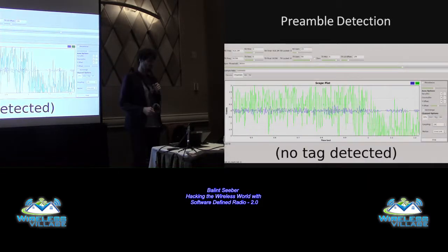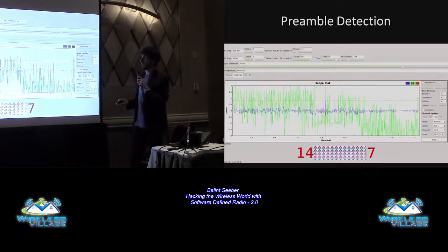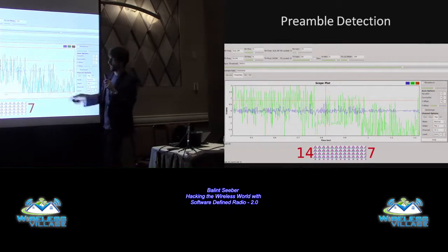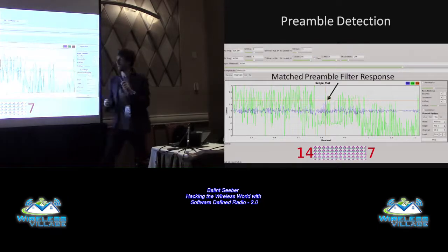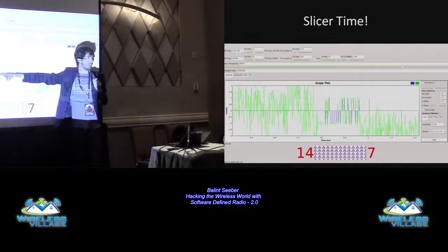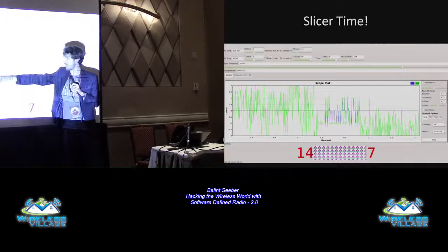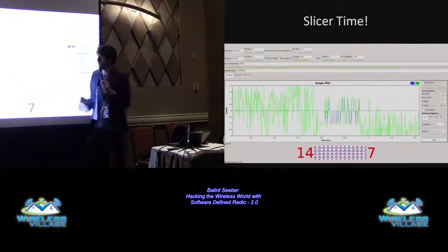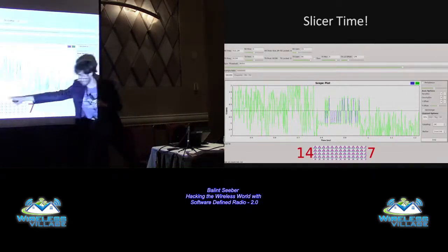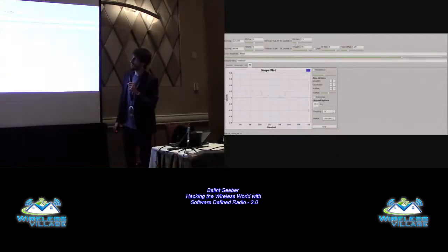And that contains your unencrypted, unauthenticated tag ID that identifies you as an individual. So this is the preamble it's looking for in that backscatter modulation. There's a fixed series of bits, and when it hits the preamble, it knows that a packet is then coming and will decode that. So as you can see here, remember, like with the frequency shift keying from the pager, you have exactly the same scenario here. So it decodes anything above and below into a 0 or a 1, and that's how you determine the tag ID. So this is a little video here to give you a better idea.